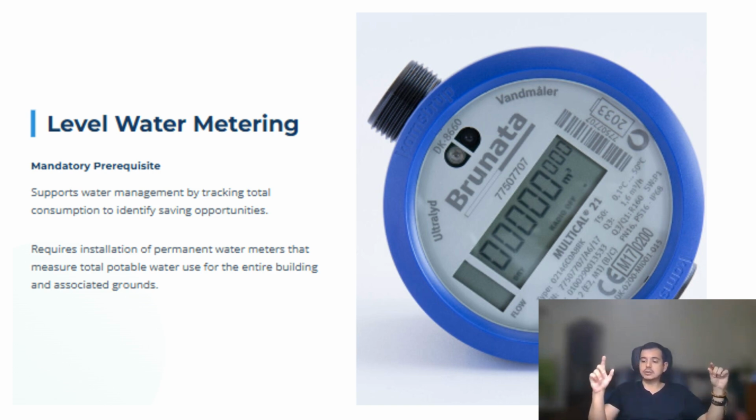Then you have the water meter, you have those pulses, then you send them via a controller, then the controller sends them to the cloud, and then you can import the data and see what is actually happening, I don't want to say every minute, but at least every 5 minutes in your building, which is way better than having someone trying to capture the information every day.